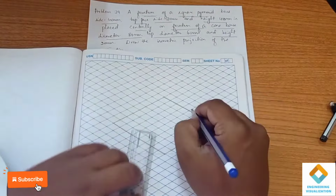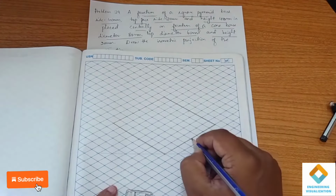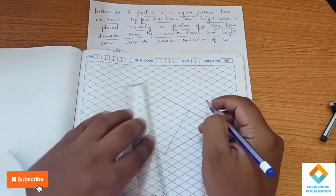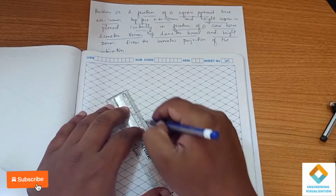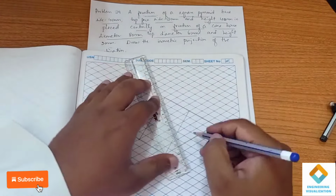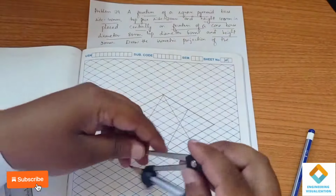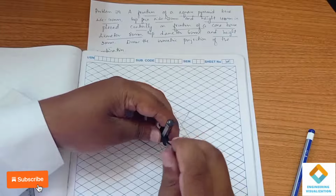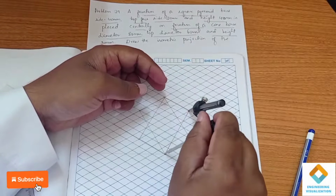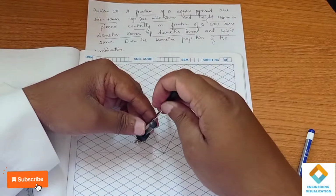So it is a cone, which means it is a circle. Circle means we have to construct the ellipse here, using the four arc by center method. So taking the compass, we can construct the ellipse here, measuring the length.